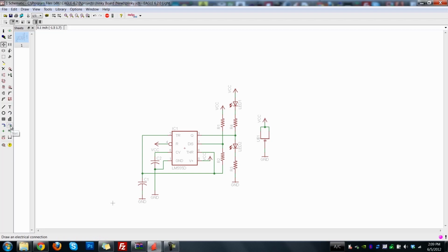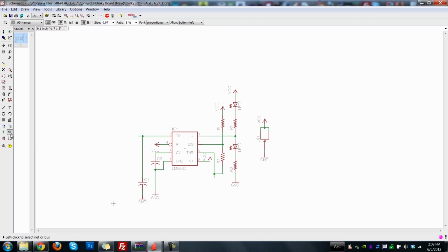So let's go ahead and delete this wire. So we want to connect this to this. So what I'm going to do is just make little connectors here and there. And then we're going to choose to label each of these nets. And by giving them the same name, it will automatically virtually connect them. So you saw before the net names are like $9, for example. So we're going to add this label to that so that it's easy for us to keep track of.